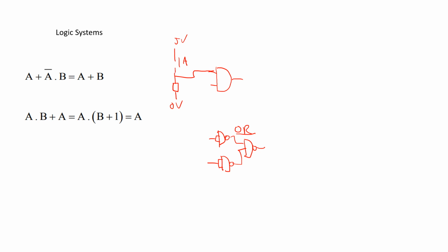You need to know when I press that switch, a logic 1 happens, so it'll be 1 when pressed, won't it? So you still need to understand what's going on. They might even give you an LED and a resistor, and then ask you to work out the resistor value. You're using core concepts, you're using Ohm's law. It's all going back to that, isn't it? Okay.